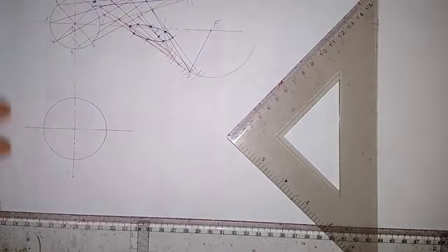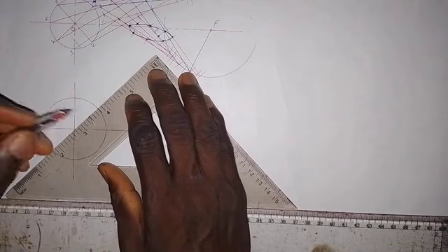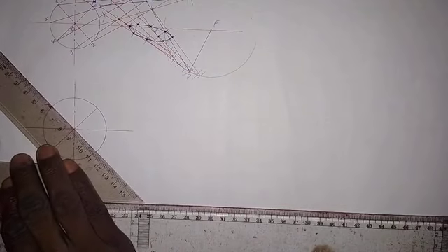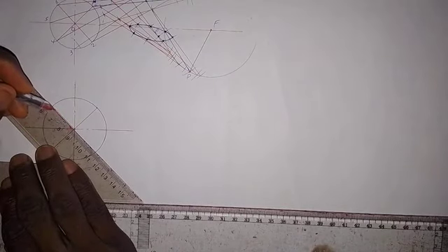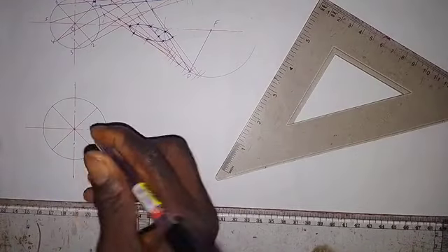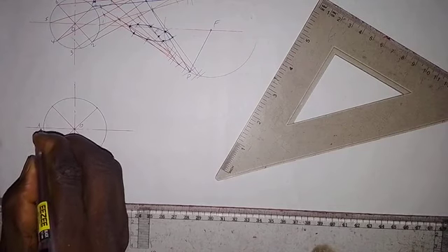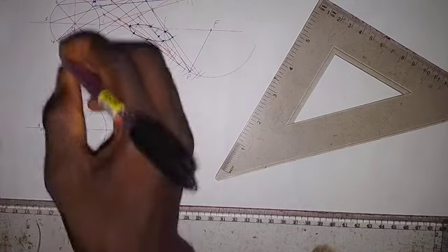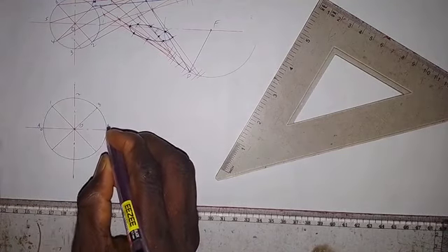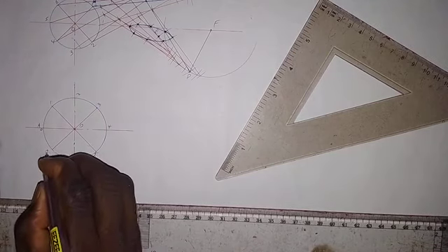Then we are going to divide the circle into 8 equal parts. Divide the circle into 8 equal parts. So this is center O of the circle, and this is point A, which is also the first point 0. Then it is going this direction. We have point 1, here we have 2, this is 3. This is point 4, this is point 5, this is point 6, and then this is point 7.